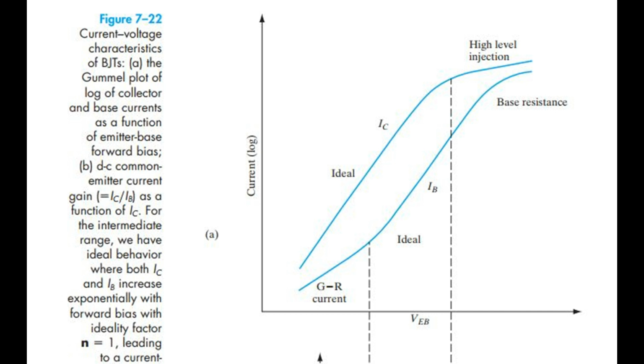This is illustrated in Fig 7.23 for a PNP BJT. Notice that the polarity of these mobile charges adds to the fixed donor charges on the base side of the base collector depletion region, but subtracts from the fixed acceptor charges on the collector side of the junction, Fig 7.23c.